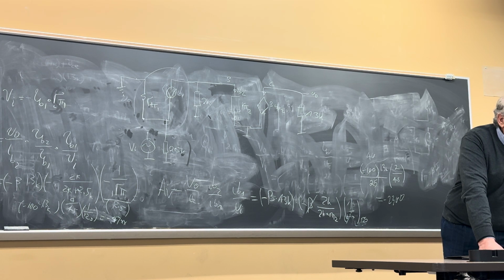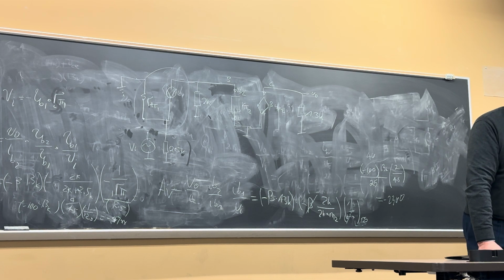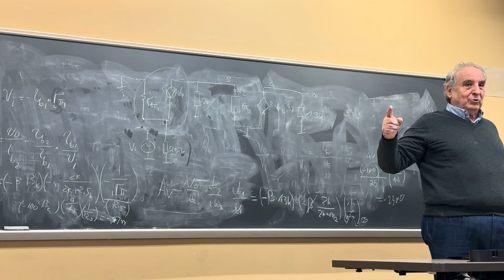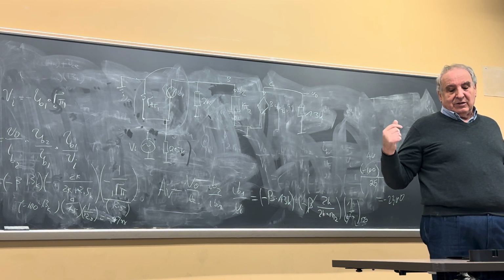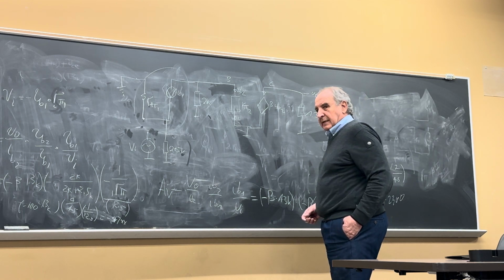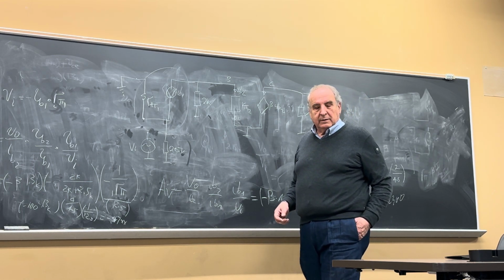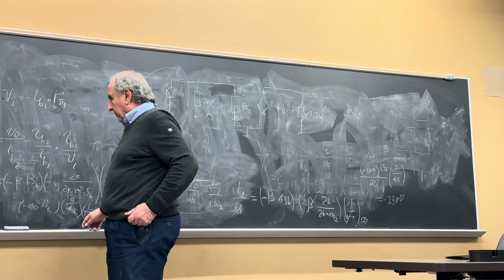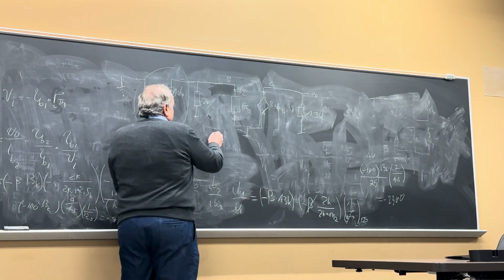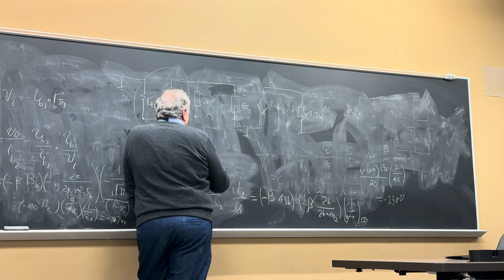So you gotta put less than a half a millivolt to see the AC signal, because this is a high gain, right? You put 1 millivolt in, it's gonna clip. It's gonna go too high and too low. Isn't it just 1.3 up and down? Yeah, sorry. 1.3 up and down. See, if you put 1 millivolt in,